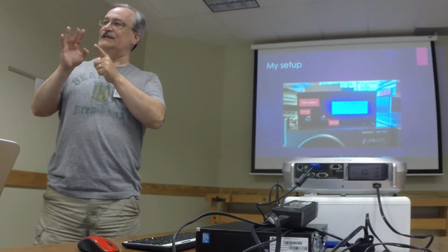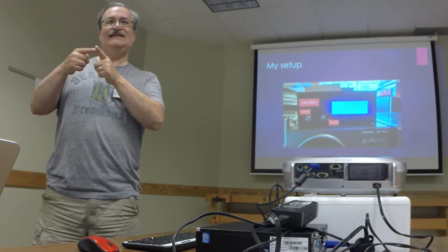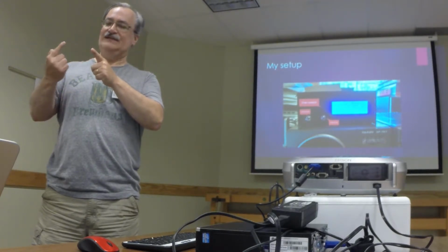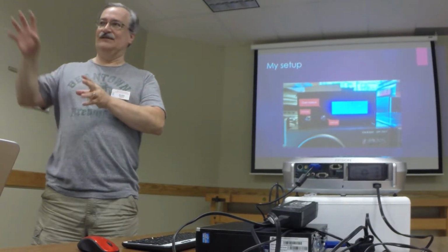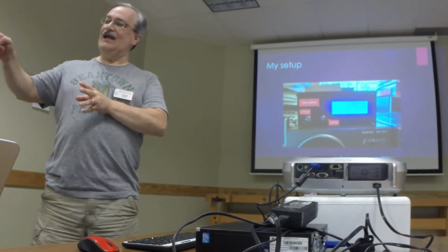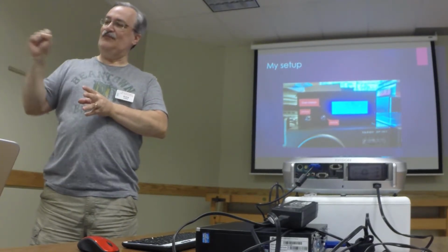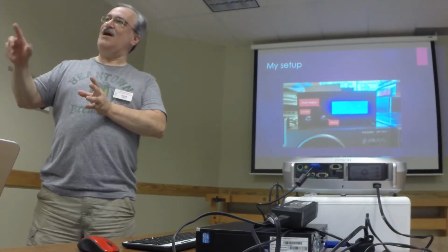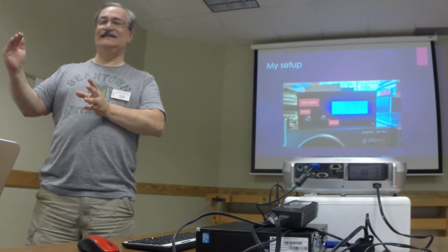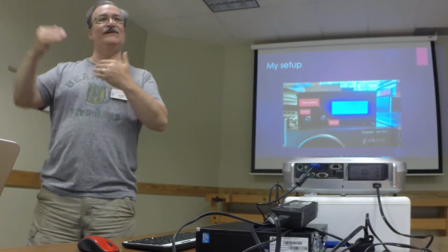So pin 4, it only needs 3 pins to rotate either direction, like most of these rotators, but it needs to hit that ground, and it does it every 10 degrees, as it turns out. And that's because the original Alliance controller that sat on a TV actually has a solenoid in it, and when that pin grounds out, it pops a solenoid, which just about makes the box jump off the table. It pops the solenoid to advance the dial 10 degrees. And that was the scheme that they came up with to keep the rotor in the control box in sync.